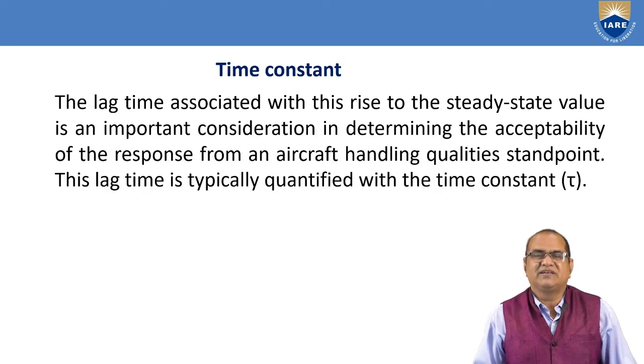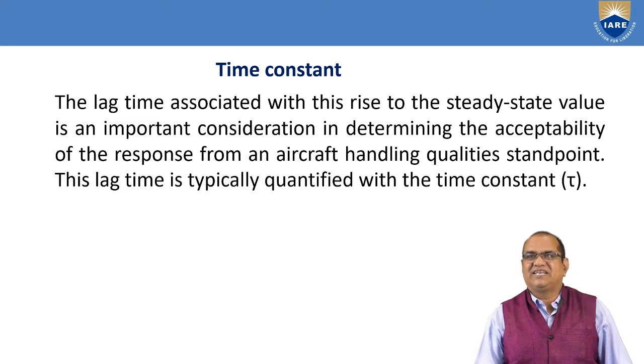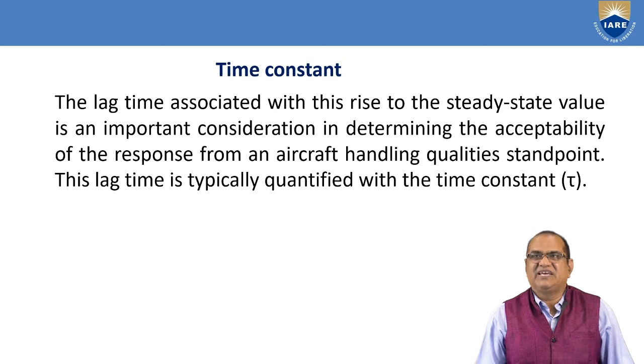The time constant, the lag time associated with this rise to the steady state value, is an important consideration in determining the acceptability of the response from an aircraft handling qualities standpoint.